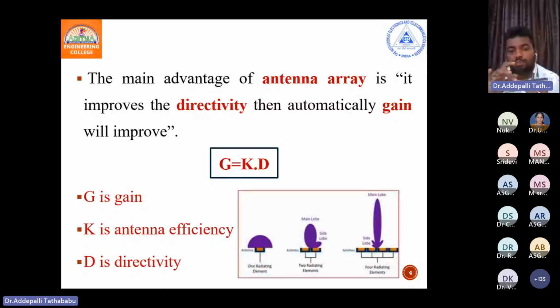It has some characteristic impedance. If you add one more component here, then the overall characteristic impedance will change. Some source is connected here. If impedance matching is there, the total power is accepted. If there are some small deviations, some part of the power is reflected back. So initially, some input power is applied.